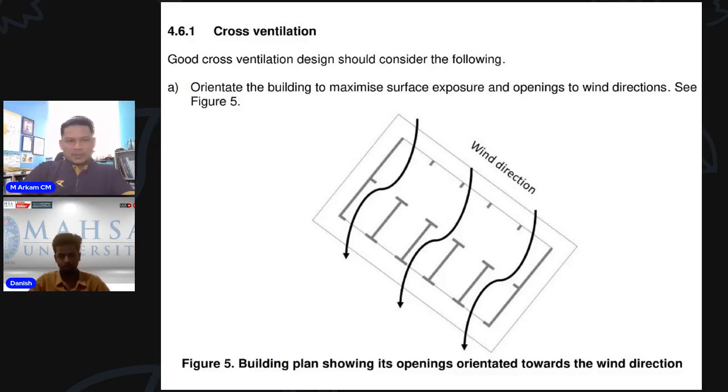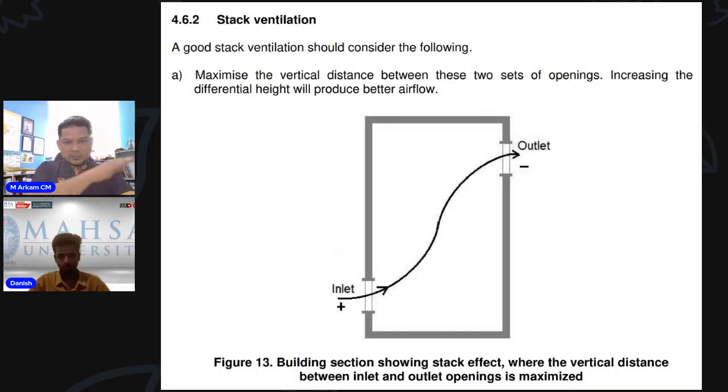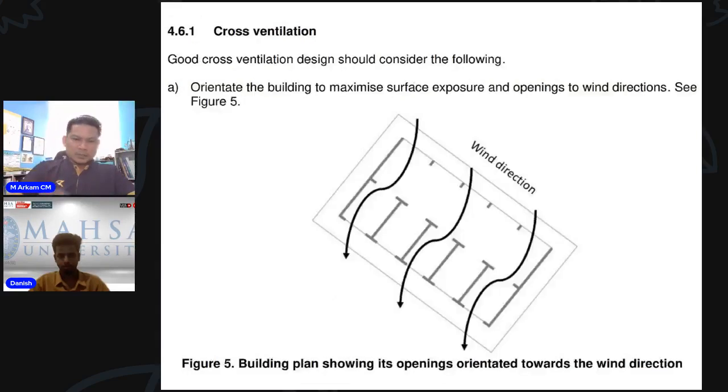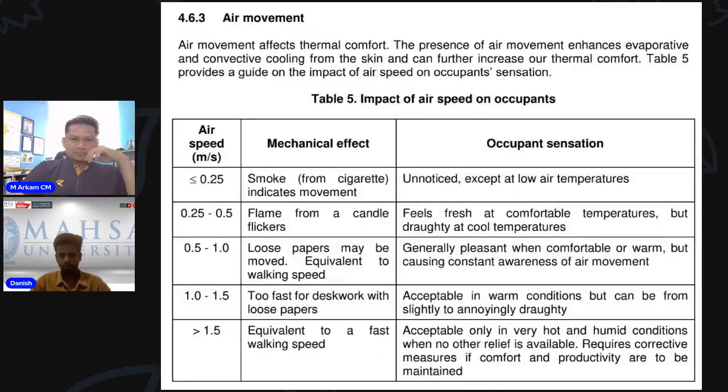This is for cross ventilation, and one more is the stack ventilation, coming from the bottom, going up and released to the environment through the second outlet in the building. So this is the Bernoulli principle, the hydraulics, as well as heat transfer. If you want to talk about engineering fundamentals, there are a lot of things to be discussed, but we just touch on it because we use building science to understand how we can position our building in the right place before we go for construction.